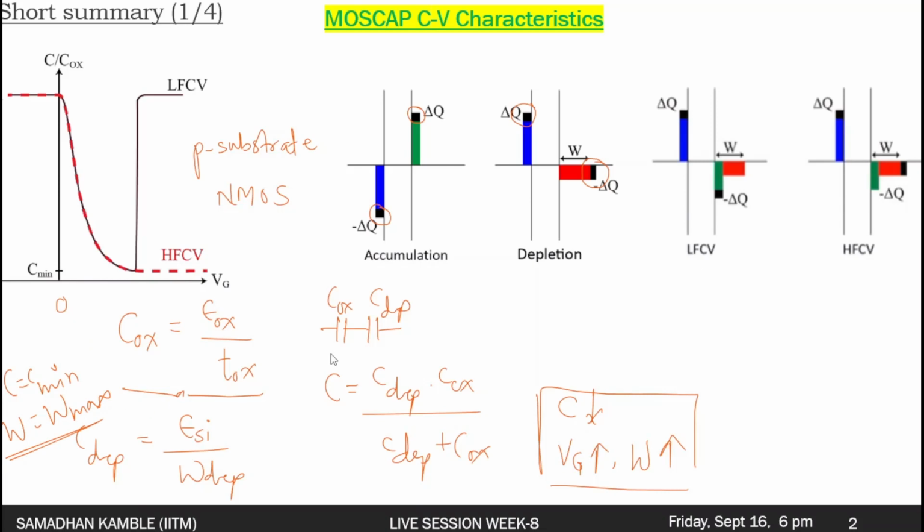Okay, so that we have covered. Also, when we go to the third region, the inversion region, we need to consider the applied signal frequency. As we know, in both the accumulation and depletion regions, the majority carrier response is needed, and the majority carrier response is quite fast, let's say in a few picoseconds. So it is very fast compared to the applied frequency.